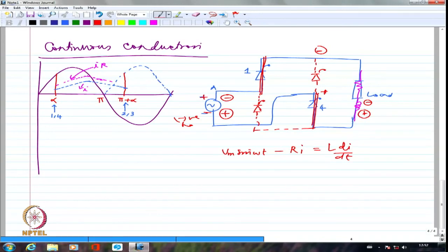So what happens is, because of the existing conduction, this negative is applied here, this positive automatically comes here, so this device is forward biased. Similarly, if I look at this particular device, this negative comes here and this positive comes through the short circuit of this here. So this device, if I may call it T2, and this T3, both T2 and T3 are forward biased because of the conduction of the previous thyristors.